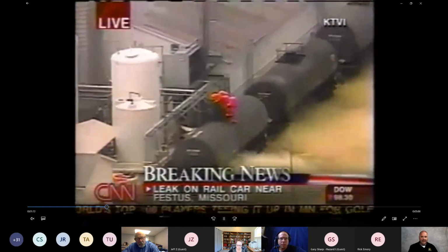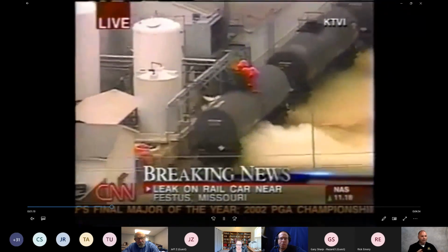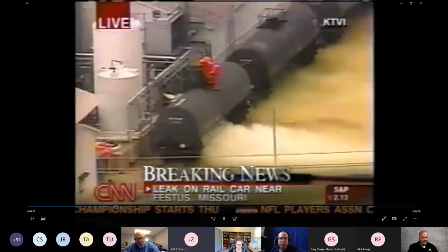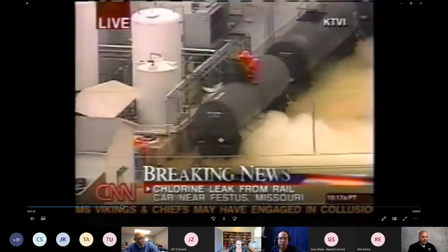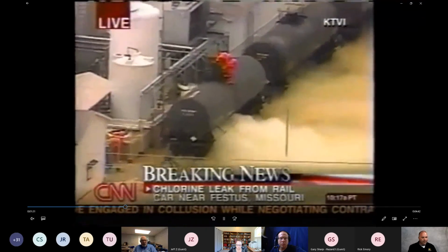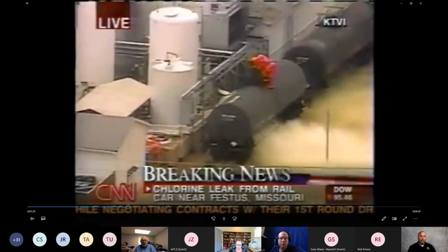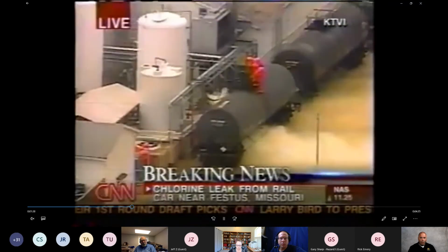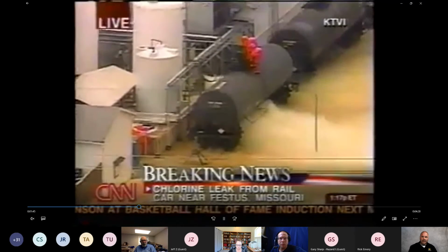The technique, and we've discussed this at length, of using a fog spray to knock this down and put it onto the ground and just have bleach is, best case, you can use it as a hydraulic push like a fan, but worst case you are not. The solubility is 0.7. You're not really doing that. So I'll buy it as a pushing agent, fine. Our vapor pressure is 6.8, so it is absolutely a gas. And one of the things that you're seeing in the video right now is this plume that's generating, and you can see the vapor density to keep it really, really low.